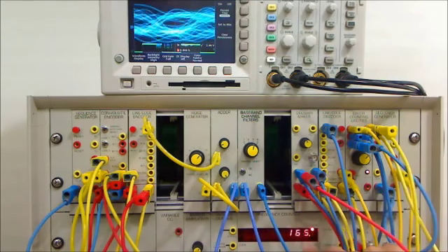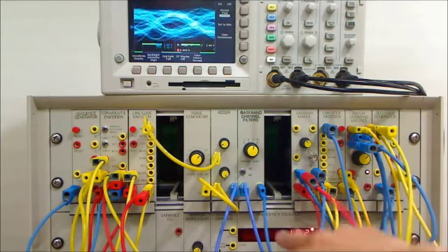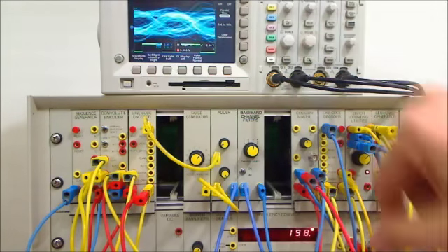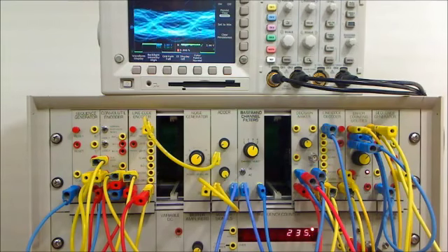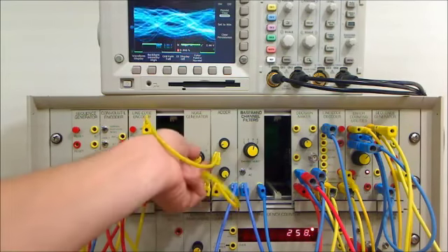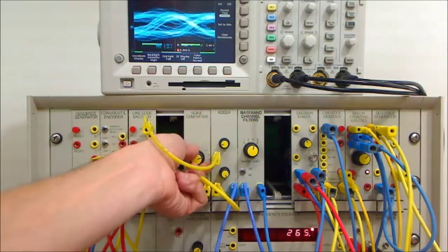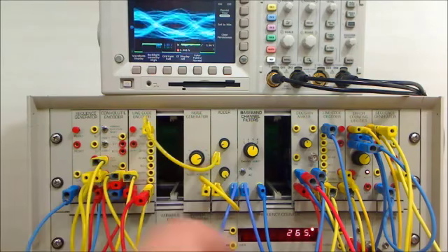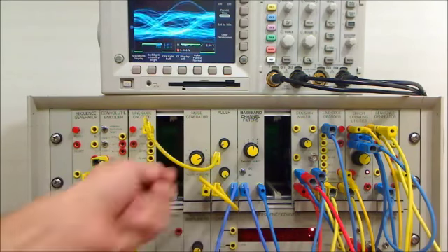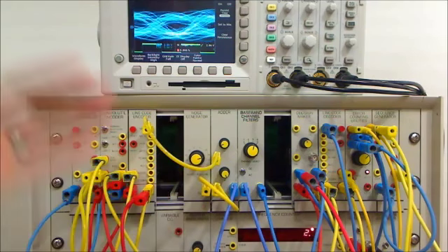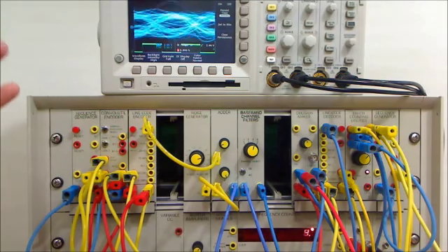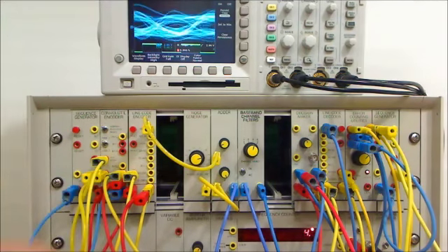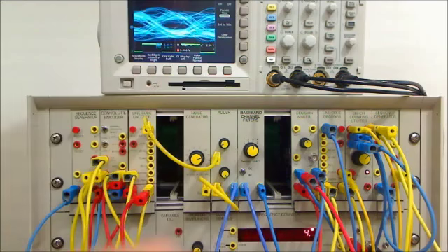We're only accumulating tens of errors per second, and you can clearly see visually that the eye is closing up significantly, whereas even just backing off 2 dB of noise already allows the convolutional coding to take effect and eliminate the errors to a significant degree.